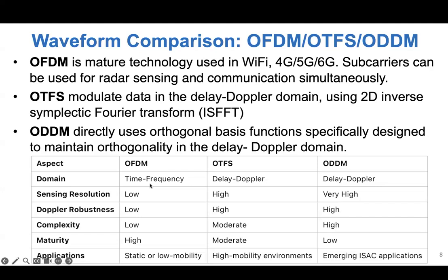However, for OFDM, the major thing is that if you have the Doppler effect, then your subcarrier sampling, I mean your timing is not good. Sorry, it's not timing, your frequency synchronization is not good. Then your carrier recovery might not be good, so you are not sampling at the peak of the OFDM subcarrier. Then you will have inter-subcarrier interference, right?